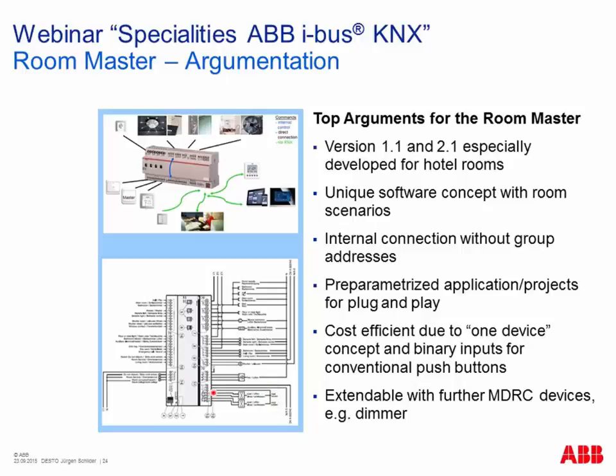One device solution, so cost efficiency is the topic here, and connecting conventional push buttons makes it sometimes even more efficient. Of course, if you need more, for example, additional DIM outputs, not available in the Room Master itself, they can be added via KNX, and then you create your individual complete solution.